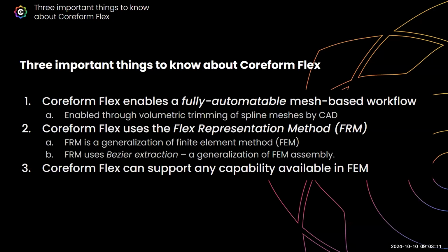In fact, studies have shown that upwards of nearly 75%, likely even more nowadays, is spent just in processes related to meshing. But this means that now you don't need to spend that time building these meshes. That's enabled through what we call volumetric trimming of spline meshes by CAD geometry.